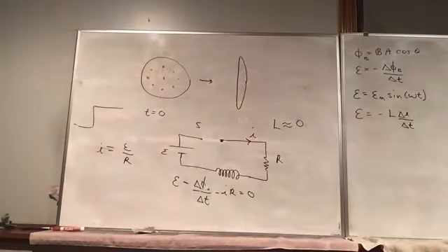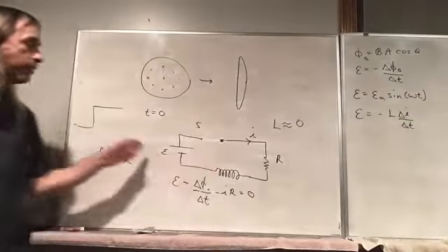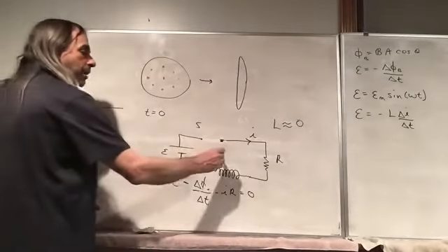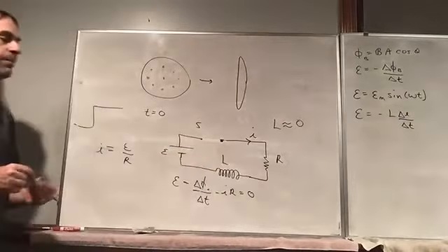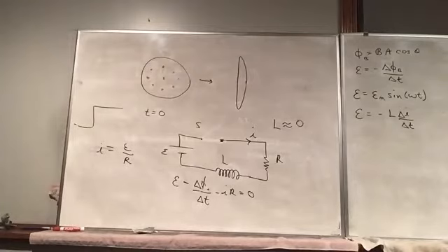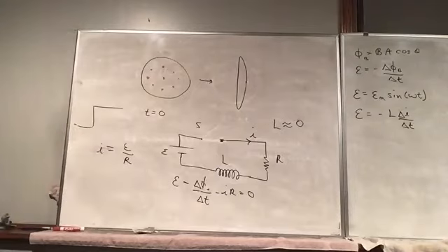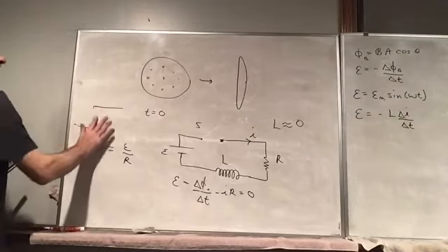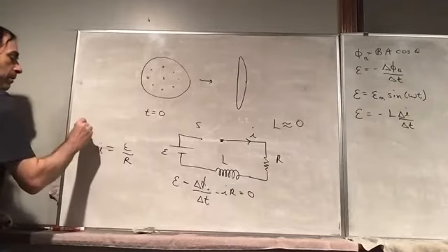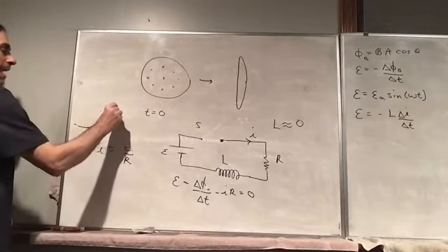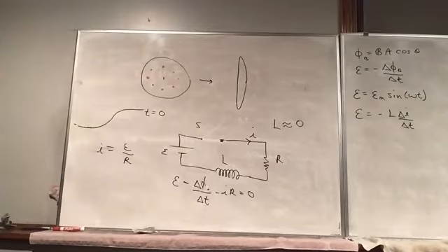That would give us maximum flux through each loop, and you can have a lot of loops. So if you have an inductor, that would introduce a certain amount of inductance into the circuit. So again, the current couldn't go from 0 to its maximum value nearly instantaneously. What that inductor would do is make that rise much more gradual.